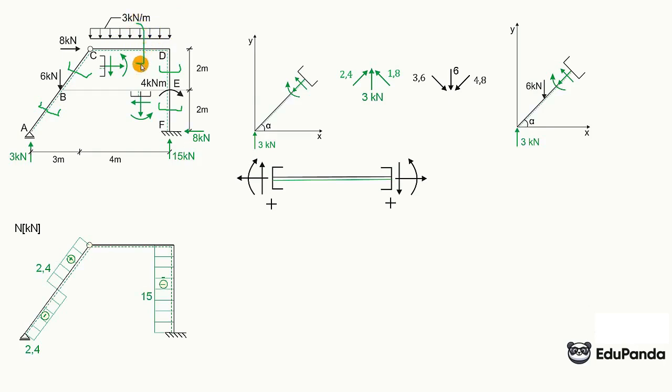We discard all that and look from the right side. We are interested in parallel forces, meaning those that stretch or compress this horizontal rod. So only horizontal forces interest us. The only horizontal force looking from this section to the right is this 8, and it acts primarily compressively. It compresses this upper rod.